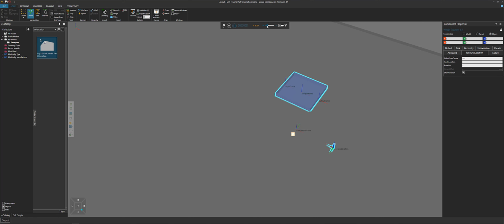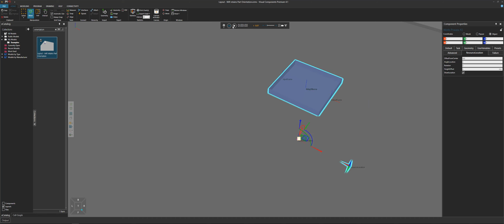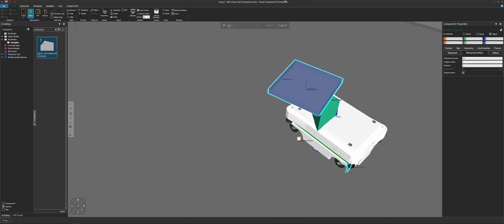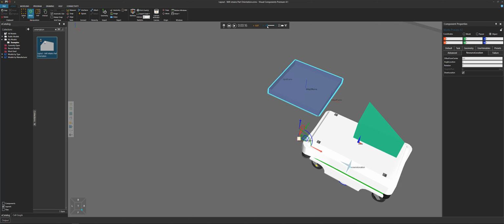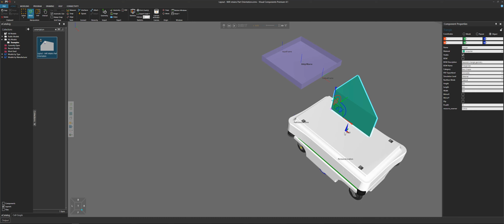So all we did was we updated the location of storing the part and changed the resource location. And there we go. So now when the part leaves the vehicle to go to this station, you can see it's retaining its orientation. It's not rotating around. So let's stop it right here. Slow it down. And if I select the part, you can see its x, y, and z axes are lined up with the pattern location here, which is also aligned with the frame or location where we're placing this part.